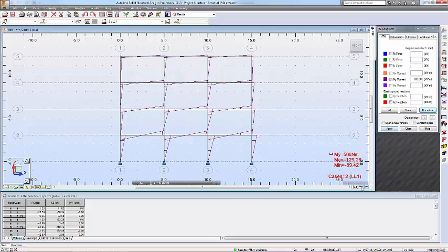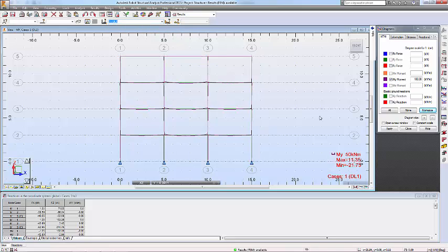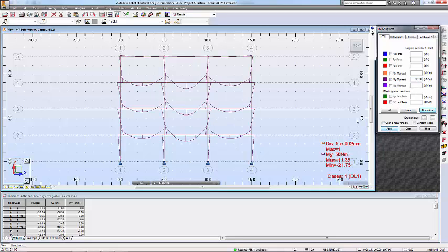Of course, we need to disable the joint displacement. That's giving you a better view of the live load or the lateral loading. What is the impact of it? So the dead load, so that's the bending moment. So you possibly want to see, and you can change the scale to see a better view. Say for example, we possibly want to change to 50, to give maybe a better view to this one. So maybe it's still not, so change to 10 and then apply to it. So that's the bending moment diagram you can see from here.